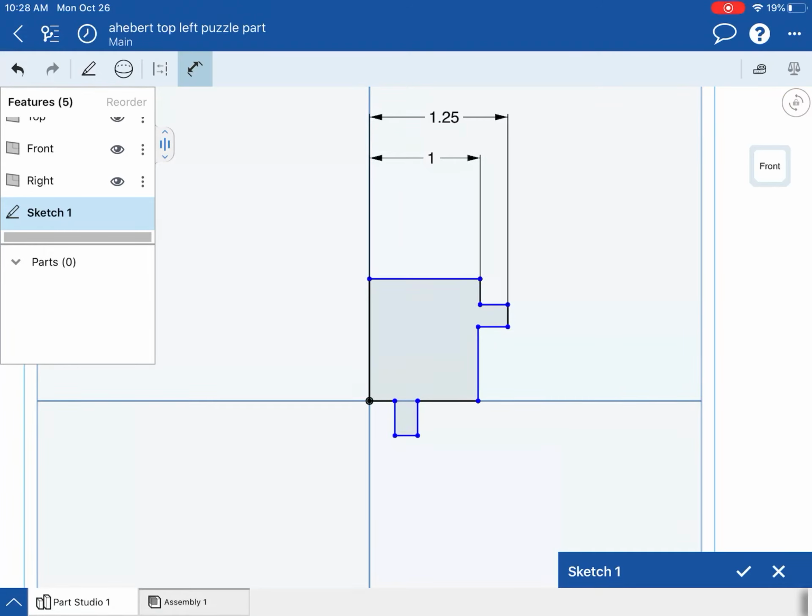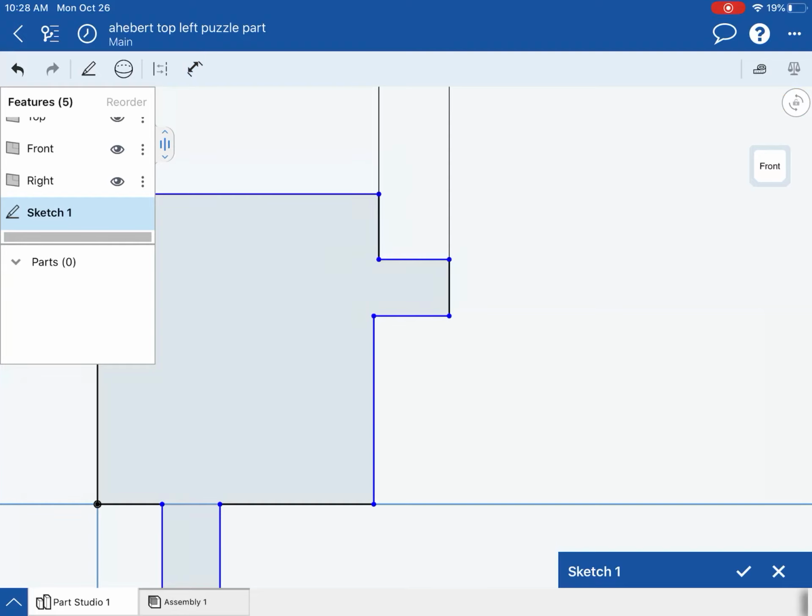If I want, I could say I need this point and this point to line up vertically, right? Oops, it started to dimension it. Let's turn off that dimension tool. If I click those 2 points and I want them to line up vertically, I can go to my pencil tool and select vertical. Okay. Now notice both of those lines are black now, and they're lined up. Black meaning they've been dimensioned. They're located. All right, so horizontally, I still need to dimension.